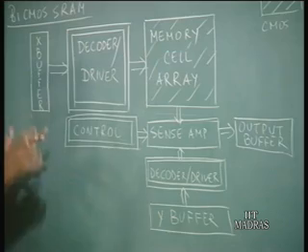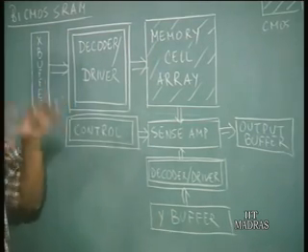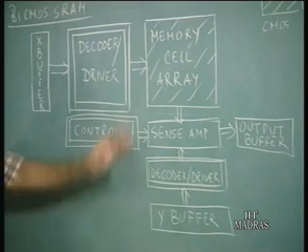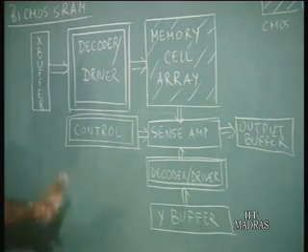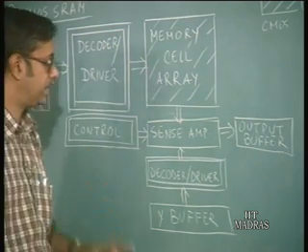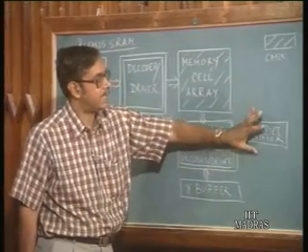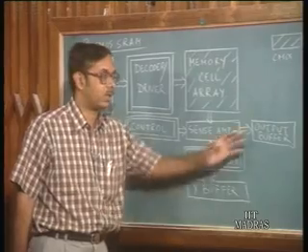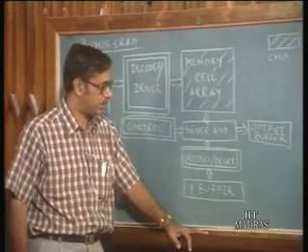So, the negative voltages are retained, but converted to CMOS levels, which we shall see in today's class. And the control circuit is also BiCMOS, in the sense it contains both bipolar and CMOS components. And the output buffer, because again it is an ECL type of IO interface, is bipolar, because the output is at ECL type voltage levels.